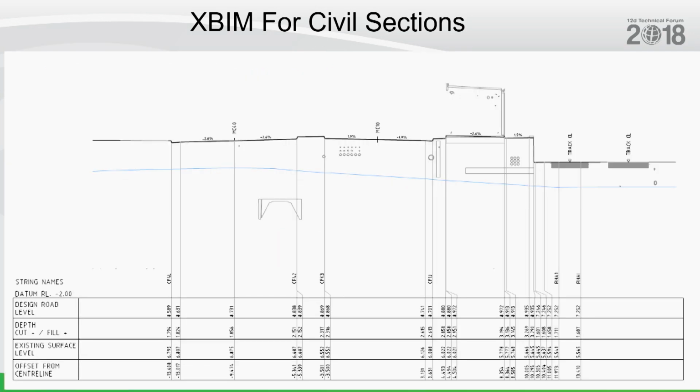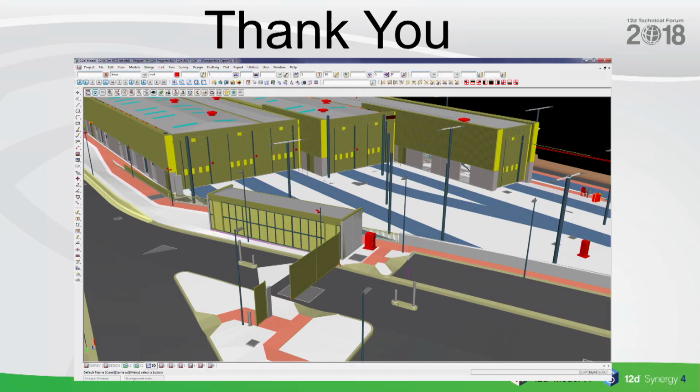Another view of how you can see the coordination of how close the conduits have been modeled to the surface, as well as the foundations that we're interacting with. This is great because typically most people for retaining walls and tunnels want a long section of that element, which Revit doesn't do. So we can spit out an IFC file to 12D and ask the civil designers to give me a long section along that wall and get all the information for us.